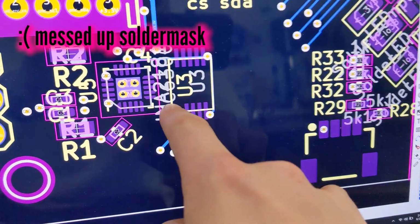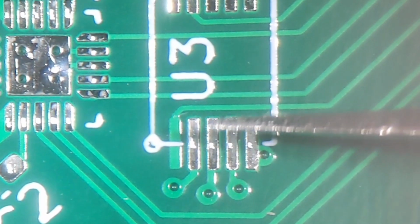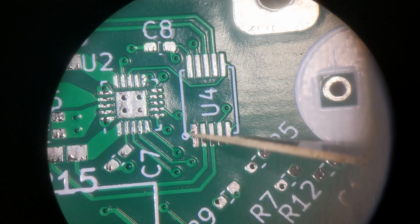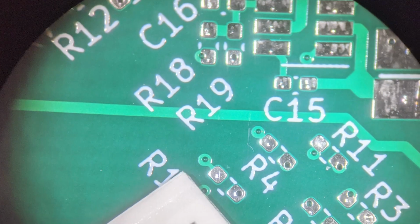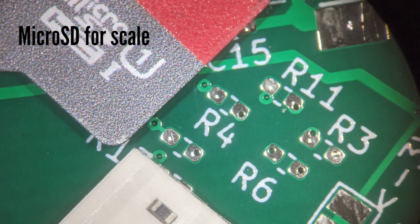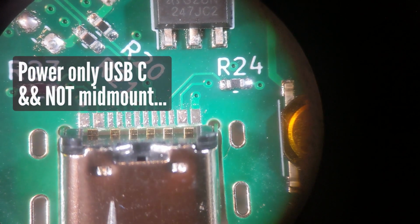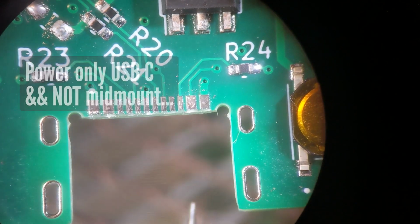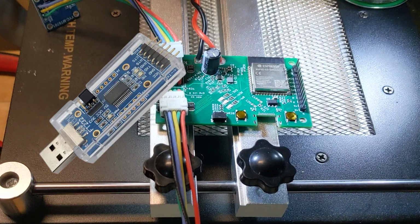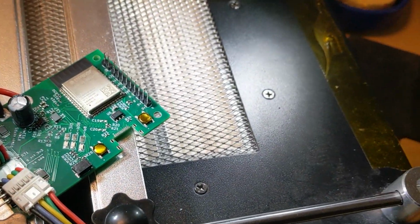I forgot to include the mask for this pin. That's just a mess up on my part. So we're gonna scrape it off. That way I can actually solder. All right, all fixed. Wasn't so bad. So then everything else is like decorating a cookie. You just take these tiny components and put them on the solder paste and then heat it up and it melts together. I did buy the wrong USB-C connector, so we're gonna have to program some other way. I threw a blink sketch on this handy FTDI USB thing that I have, and then programmed it with the pins on the side of the board, and lucky for us, it worked first try.